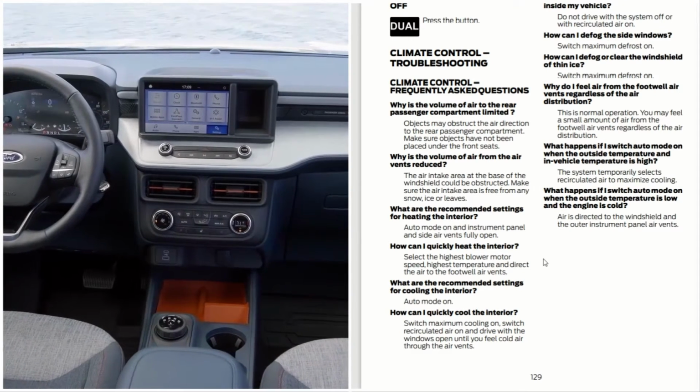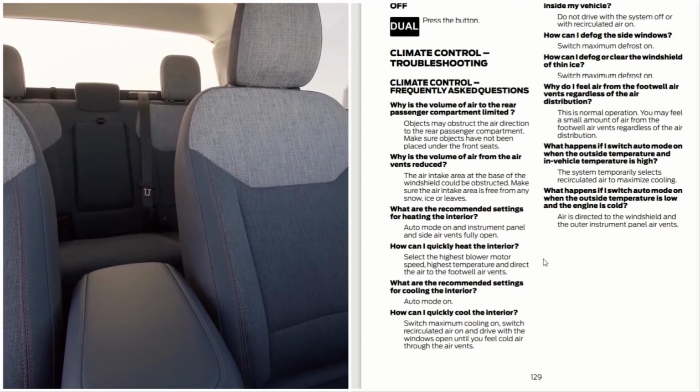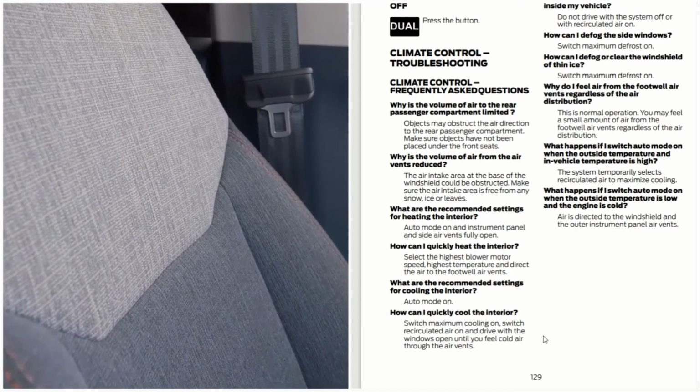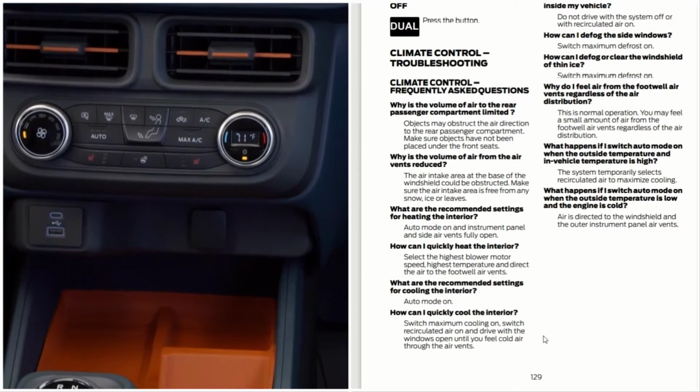What are the recommended settings for cooling the interior? Auto mode on. How can I quickly cool the interior? Switch maximum cooling on, switch recirculated air on, and drive with the windows open until you feel cold air through the air vents.